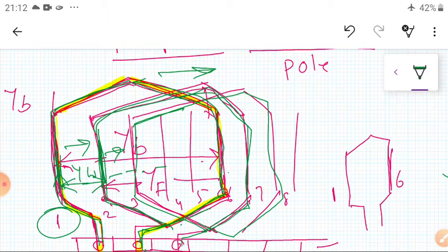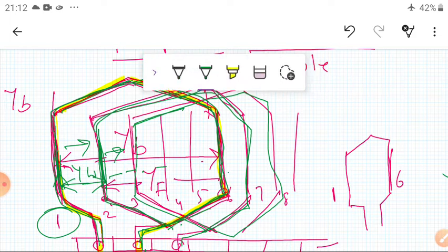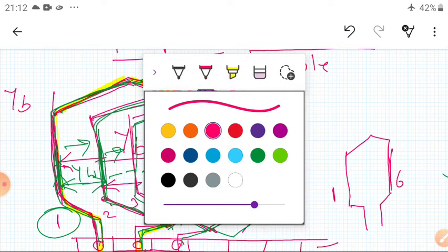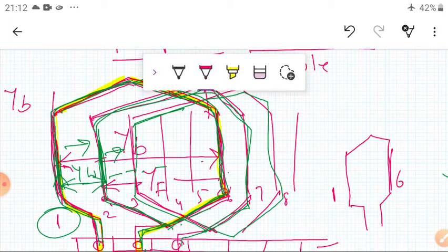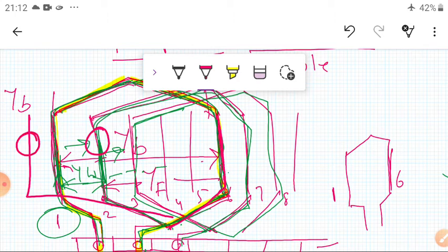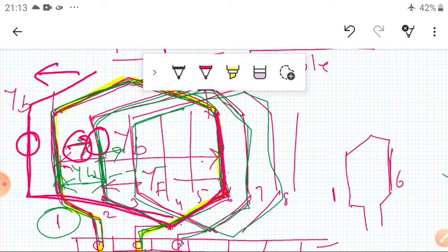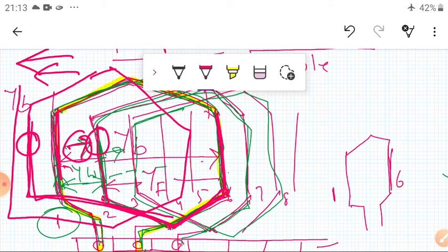So instead of this winding, suppose I place this winding, connected here. Instead of going in this direction, for example, this coil is coming here. Instead of going to this one, if this winding is connected to this slot, what will happen? It is moving in this direction. Previously it was moving in this direction, now it is moving in this direction. This winding is not connected here, it is connected to the left side of this main coil. Next it is connected here, and then goes to this winding. That means it is a retrogressive winding.